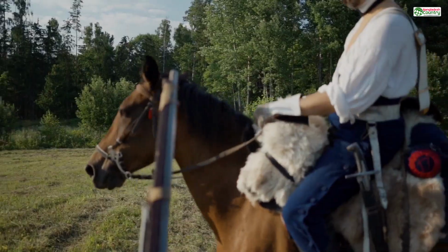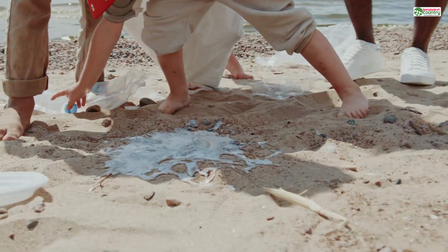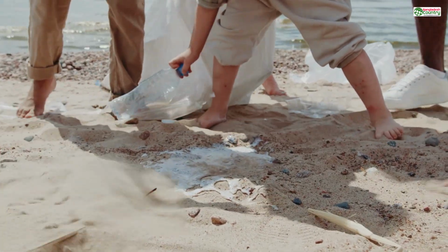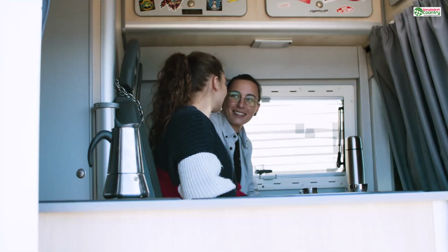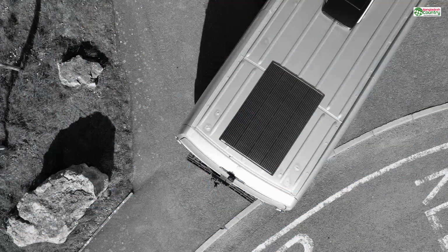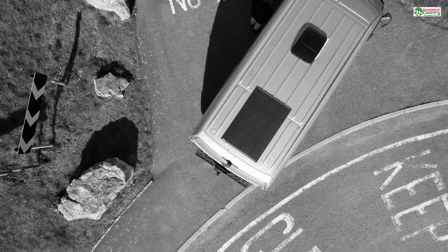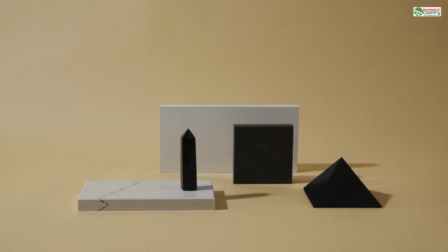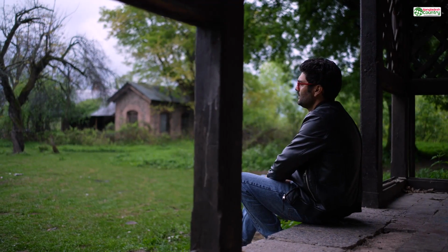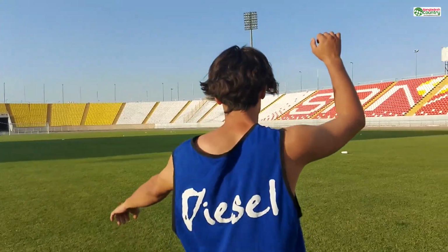The third horseman is the trickiest to understand, but it's responsible for some of the most baffling print failures. It's called a flipped normal. Now stay with me here. Every single flat surface or face on your 3D model has a direction. It has an outside and an inside. This direction is called its normal. Think of it like a tiny arrow pointing perpendicularly away from the surface. For a solid object, all of these arrows should be pointing outwards, away from the center of the model. A flipped normal is when one or more of these faces gets turned around so its arrow is pointing inwards.